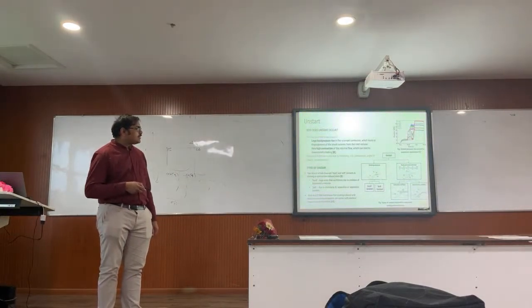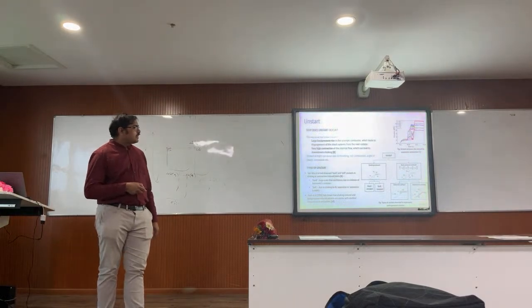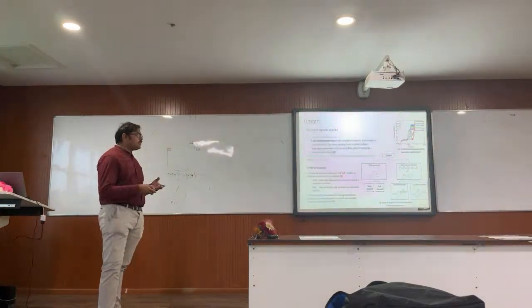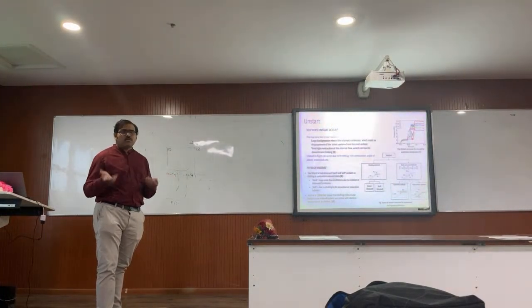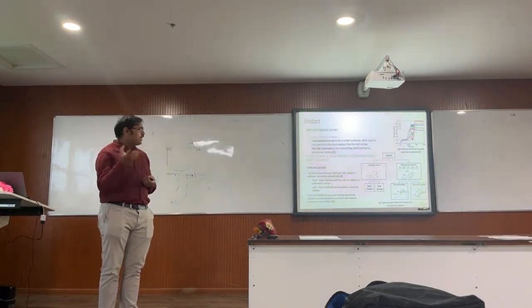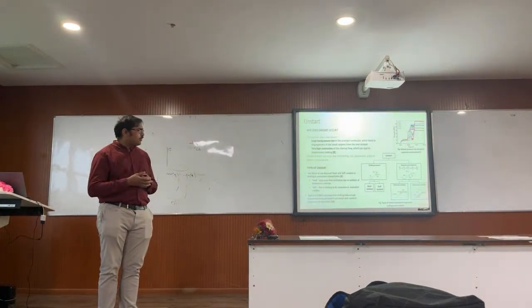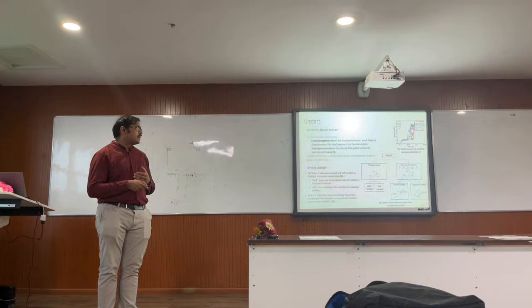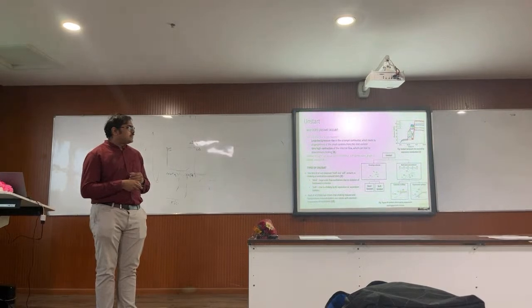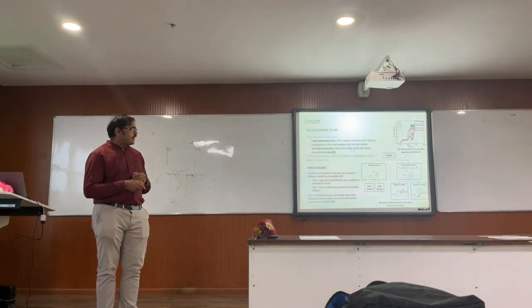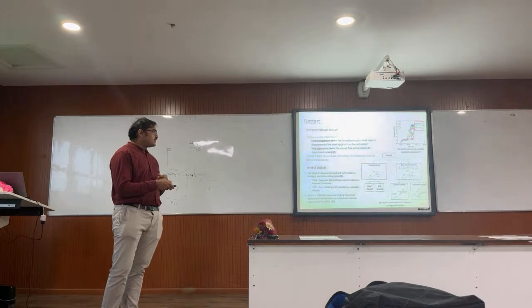The unstart itself can produce a spillage. So when unstart happens, the incoming mass flow is much higher. The intake is not going to take in that mass flow, so it will spill out. It's like an overflow. The spillage can happen either by subsonic means or by supersonic means. Subsonic spillage means the shock waves are very strong ahead of this. It has converted high supersonic flows to subsonic flows, and then it will spill.